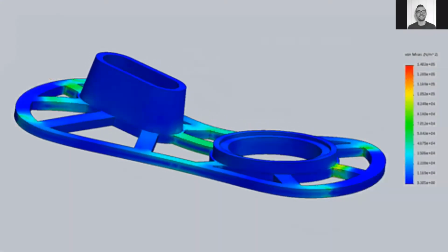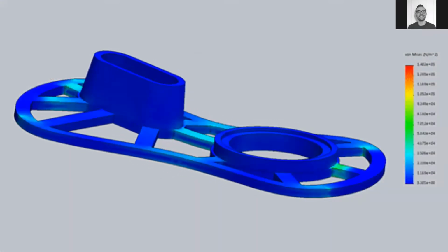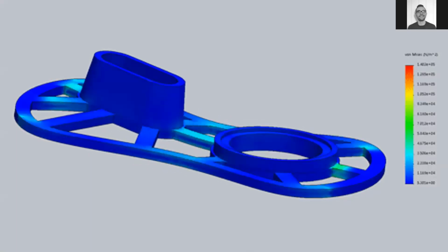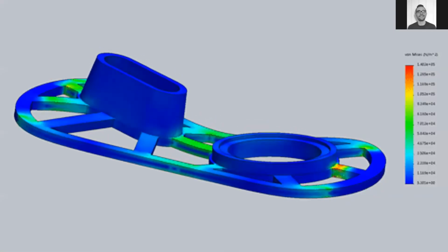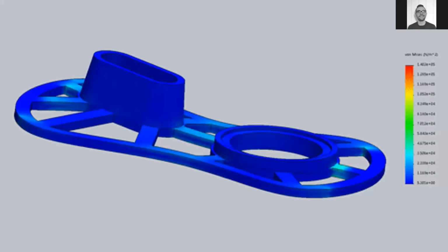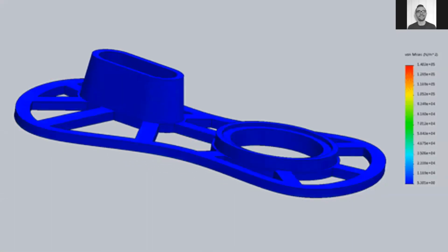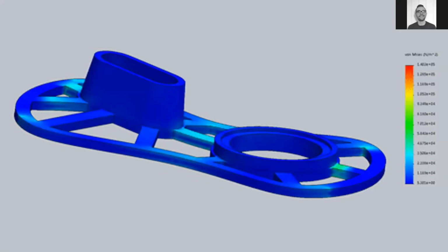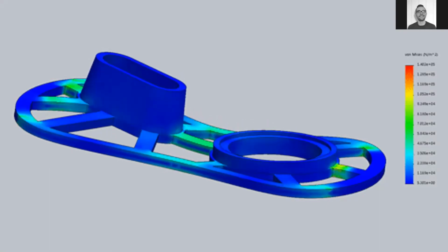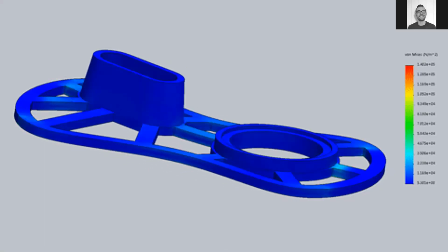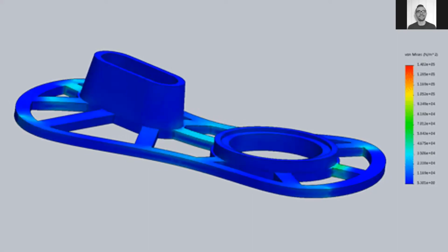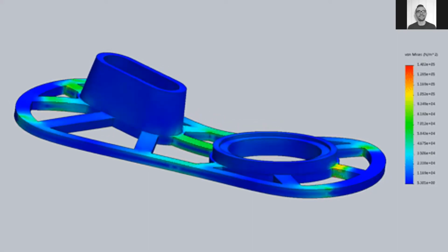and grip points. Now, when we run this through FEA analysis and the flex that's likely going to go under as we're starting to polish, we can see that the part has some flex. This is assuming 100% density, so we know that if we're going to print this in a sparse infill or sparse double dense, the potential force and the potential for flexion in the part is going to be even more substantial. And so we can see here in the parts that are highlighted in the green and into red areas while it's flexing, that if we print this in full sparse, we're likely going to need some adjustments and some improvements.